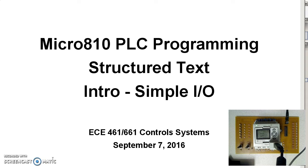Next, I'd like to look at a different type of programming called structured text. Structured text is similar to C programming, actually more similar to Pascal programming for the Micro 810 PLC. I'd like to look at first some simple I/O. Have the output equal the input pin and some if-then statements.